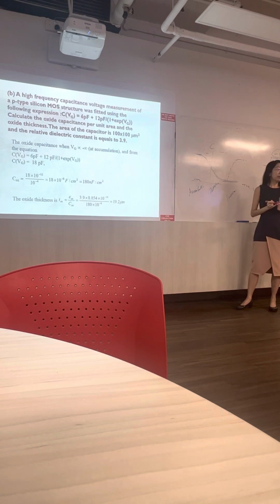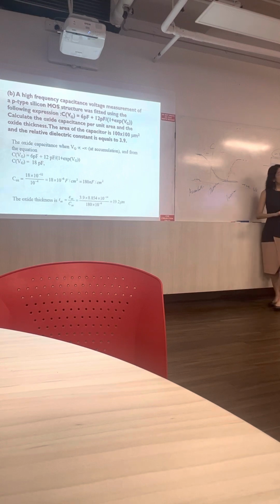Depends on the application. Because if you use it for MOSFET, you'll be operating on the accumulation side anyways, so you'll be more logical to pick that side. For the BJT side, you want the minority carrier, so you will select from the inversion side. Inversion actually is very useful. Many transistors are operated under inversion, actually. When you have a turn-on voltage, you're using a minority carrier.